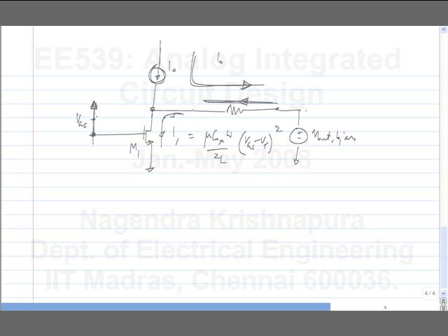Now that is what the stage can provide. Now you need to see what the load needs. That depends on the swing here. You have a certain swing at the output. The peak to peak swing divided by the load impedance at the frequency of interest will give you the peak to peak current. So half of that peak to peak current must be the bias source, at least half of that. It needs to be a little more than that. Things cannot completely cut off. Is this okay?